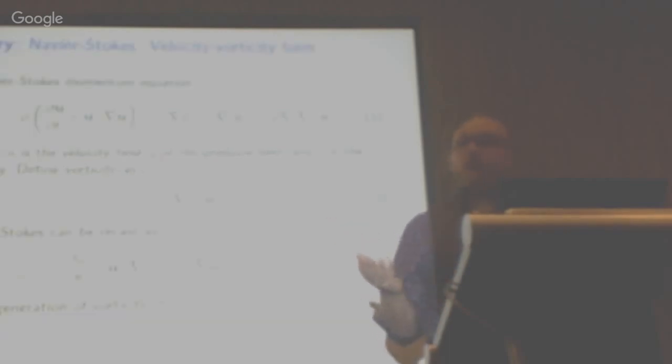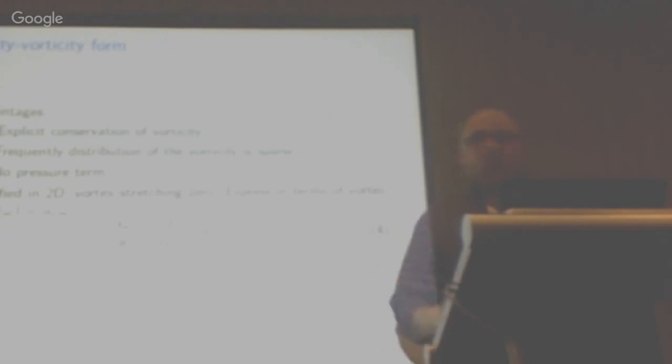So at its core, we have Navier-Stokes. If you think about vorticity, the quantity omega there, it's just the curl of your velocity field. If you were to plug this back into Navier-Stokes, you can recast it in a velocity-vorticity form here, where you lump all viscous generation of vorticity into a source term. There are three components: one is the time dynamic portion, one is transport of vorticity, and the other is vortex stretching. I'm not going to touch much on vortex stretching, because in 2D it doesn't exist, which is a nice simplification early on.